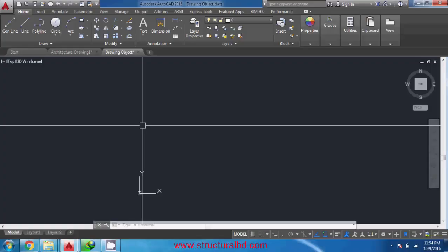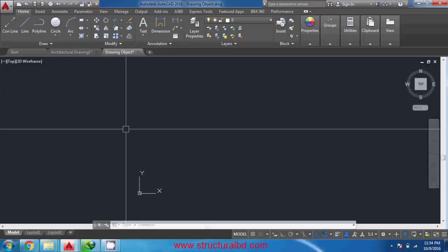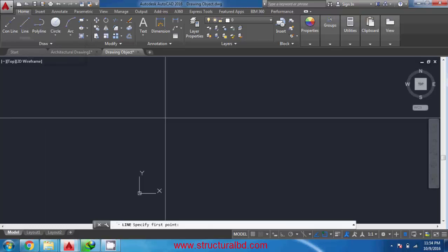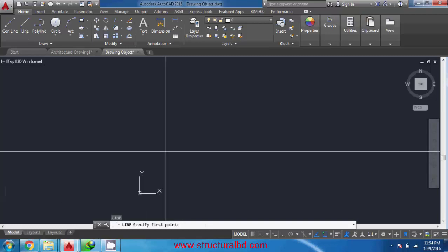In this video I will discuss the line command. To start with this command, go to ribbon tab Home and click on Line to activate the command, or you can write L, enter to activate the line command.